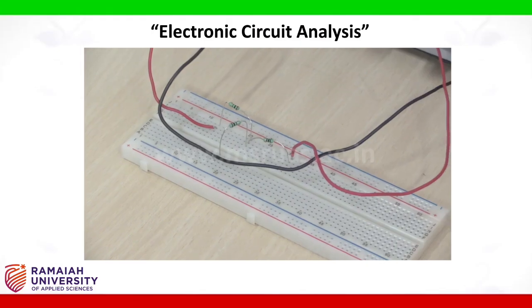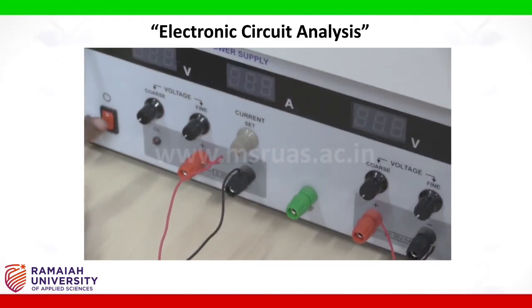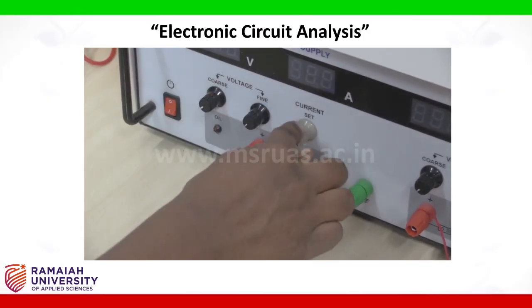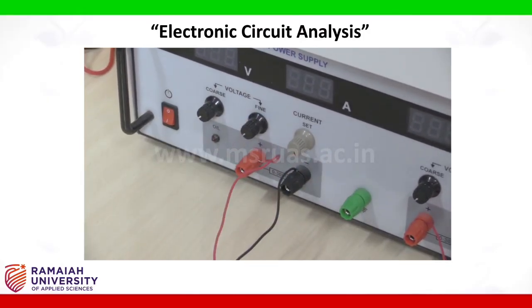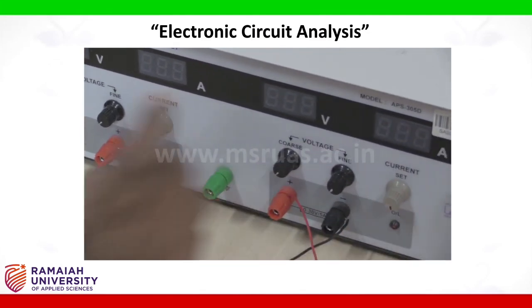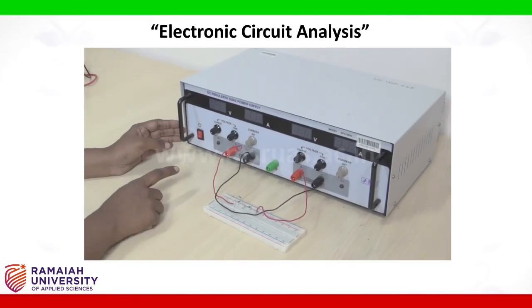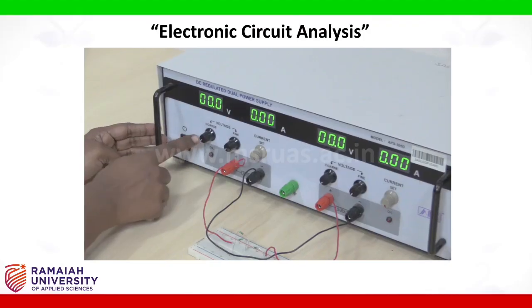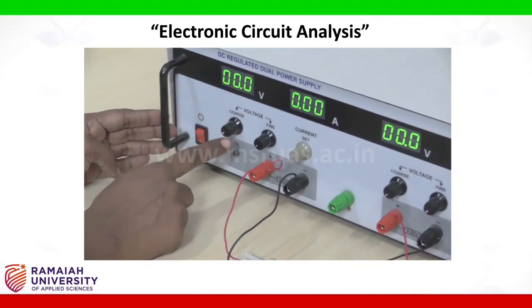Before switching on the power supply, we have to put voltage in the minimum, current in the maximum. Voltage in the minimum, current in the maximum. Now switch on the power supply. Source 1 voltage, let it be 10 volts.